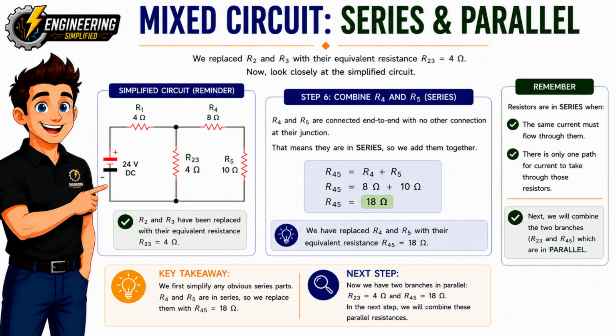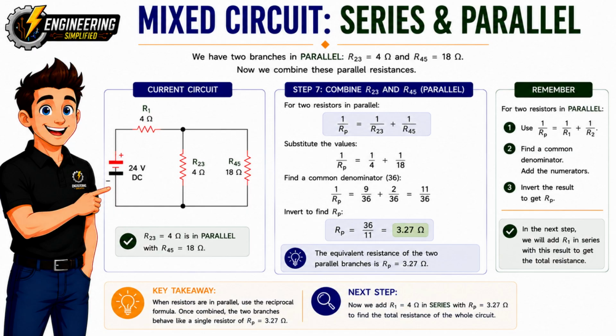So we can now replace R4 and R5 with a single equivalent resistor called R45 with a value of 18 ohms. Our circuit is becoming much simpler. Instead of 5 separate resistors, we've now reduced the circuit to just 3 equivalent resistances. In the next step, we'll notice that R23 and R45 are now connected in parallel, allowing us to simplify the circuit even further.